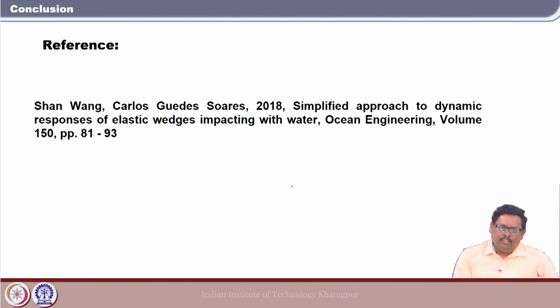So in this class we discussed how you can incorporate the non-linear slamming load, and in the previous class we discussed how you can incorporate the green water load into your boundary element solver. This is the advantage of the time domain boundary element solver. In a frequency domain solver you cannot do this.